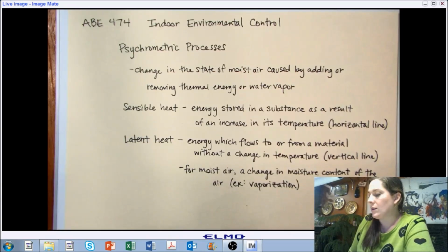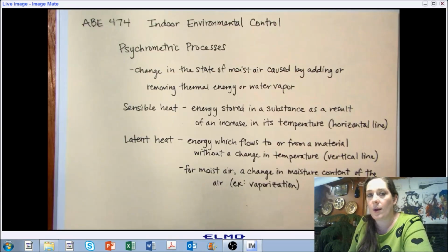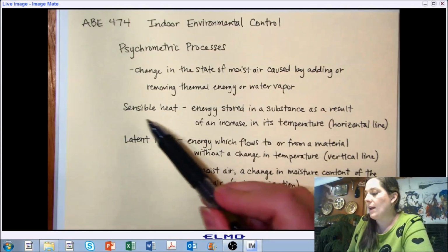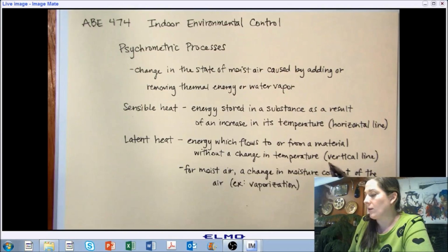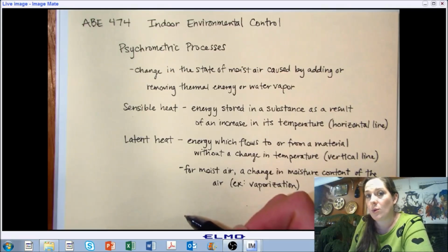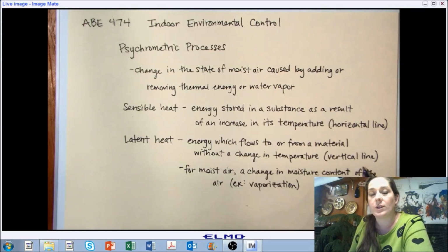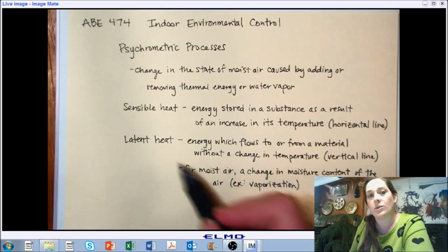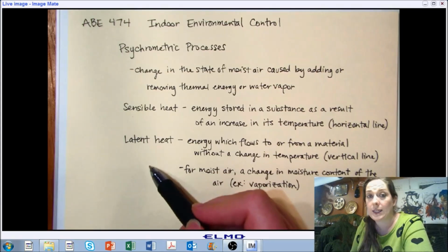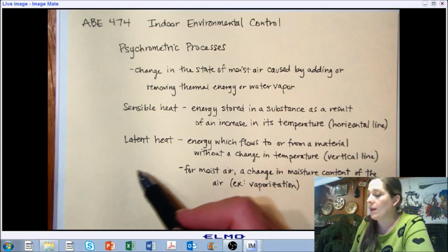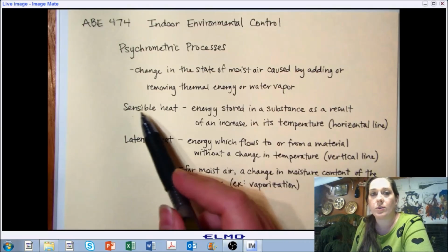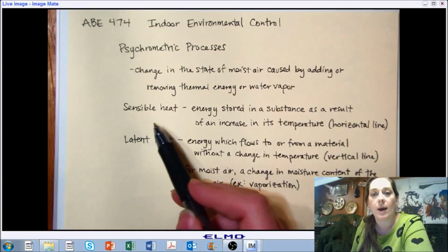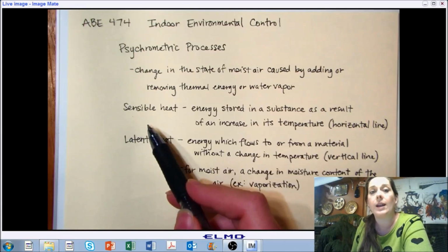We're going to get into the specific processes for moving from one state to the other, and moving along lines of sensible heat, so horizontal line or a vertical line, you can't necessarily move straight along the line in this direction. In most of our cases, our processes are some combination of sensible and latent heat. So while you may want a certain amount of change in latent heat, you may also have to recognize that it's accompanied by some amount of change in sensible heat, and vice versa.